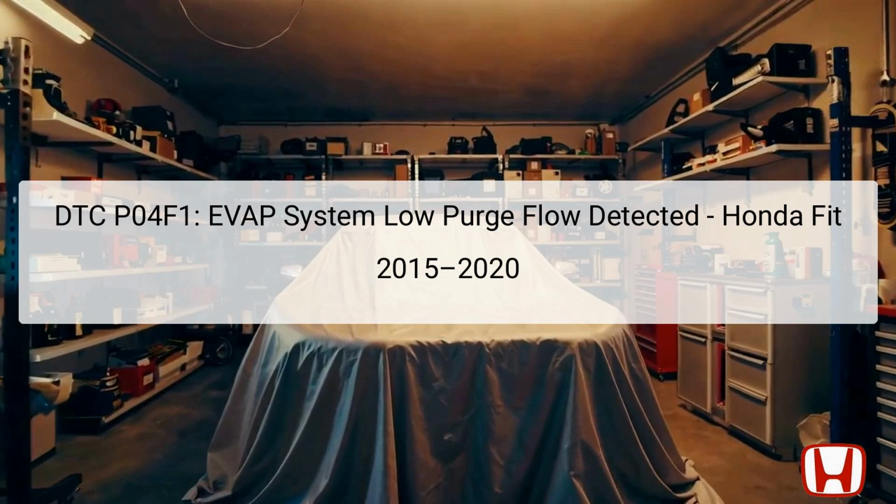The EVAP system is crucial for controlling emissions from the vehicle's fuel system, preventing fuel vapors from escaping into the atmosphere. The system includes components such as the EVAP canister, purge valve, vent shut valve, and the fuel tank pressure sensor. These components work together to capture fuel vapors, store them, and then direct them back into the engine for combustion.